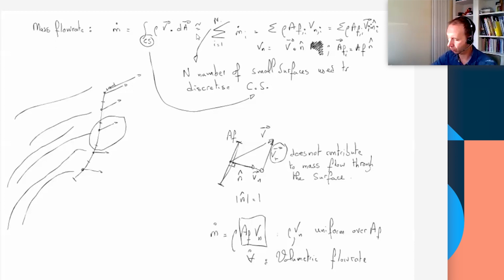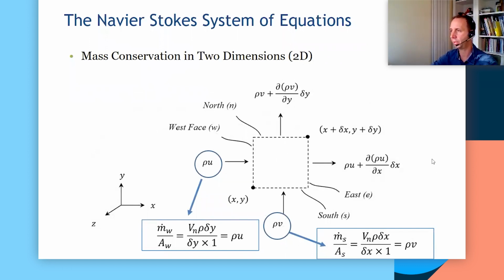Okay. So for example, the discrete area i, this one. If you multiply the area by the unit normal vector, so these two quantities multiply, you extend the length of Ni in proportion to the area itself. So the area vector is a vector whose magnitude is the area and direction is the direction of the normal to the surface. So that's the explanation of this quantity. So it's a little bit long, but it's important, and it's useful to understand what we have on this slide here. So what are we calculating there?